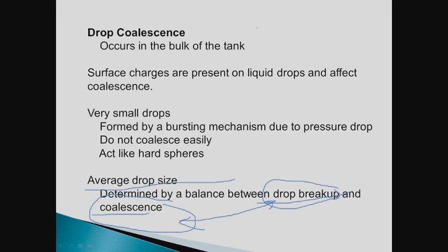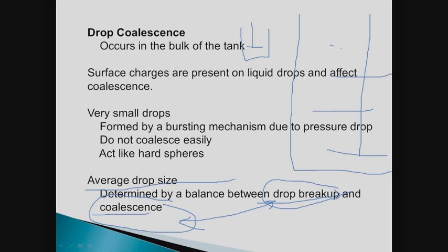See, if I take a look at my grinding operation, I had this one little grinder here. Small scale worked fine. Large scale it failed. So I got to come in with a lot more grinding discs. Basically, the problem with the drop breakage or the grinding was, if it was only one disc, it was very small in volume, and the coalescence was huge.